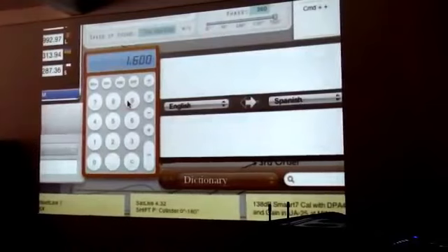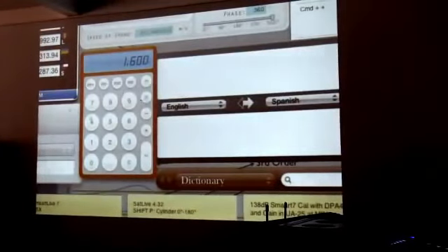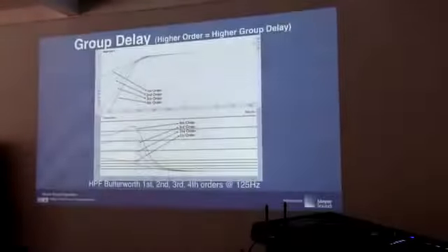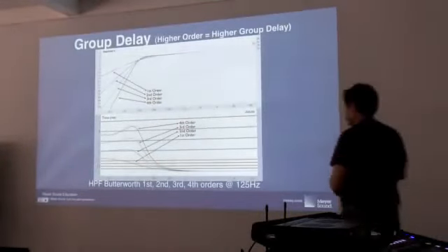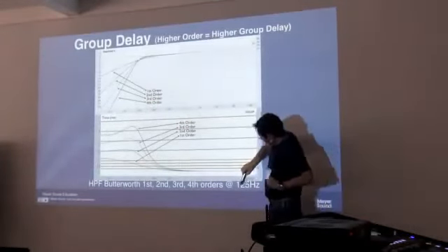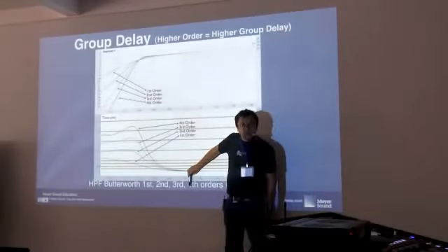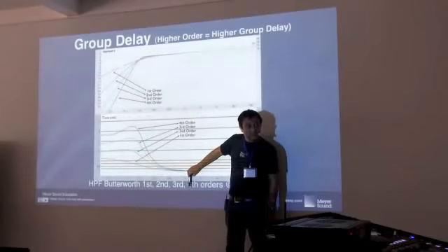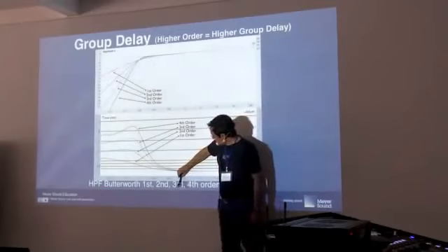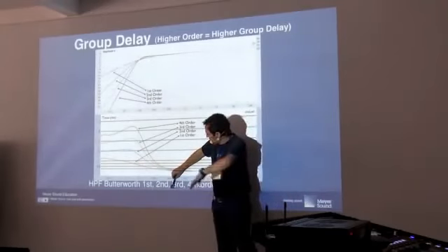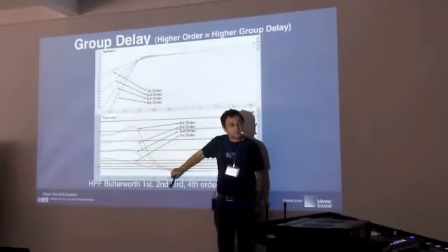It's a brick wall filter. So this means that if you select 1.25, then you can move the high pass down only to 1.6 kHz, with a roll-off of 96 dB. But if I move lower, the roll-off is reduced to 48 dB, 1 octave lower.